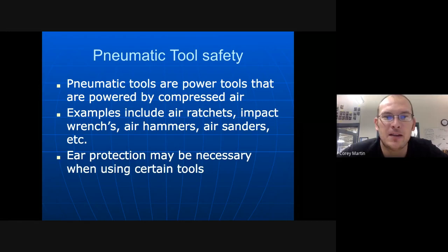Ear protection may be necessary when using certain tools. So there is one thing that must always be worn, safety glasses. Safety glasses must be worn anytime we're out in the shop. But ear protection is not necessarily mandatory until you get to a certain noise level or decibel level. But there are some people who may be a little more sensitive to the noise than others. For instance, if someone wears hearing aids, they are going to be driven absolutely insane by the noise in the shop. So it may be necessary for them to turn those off or wear some type of earmuff so that they're not just getting blasted with all that noise.